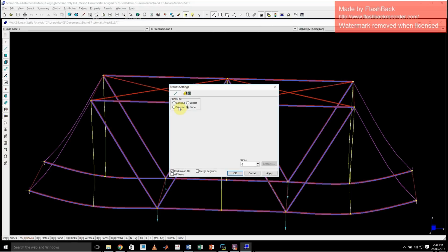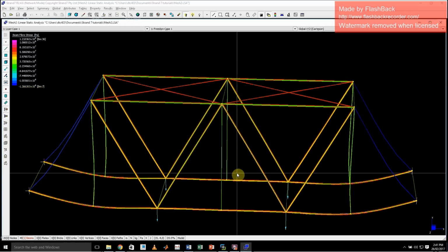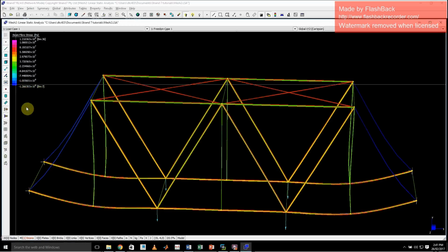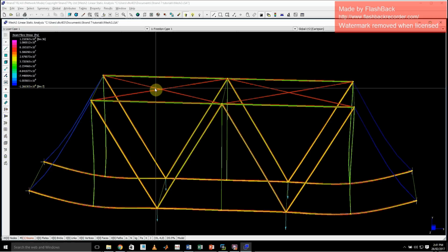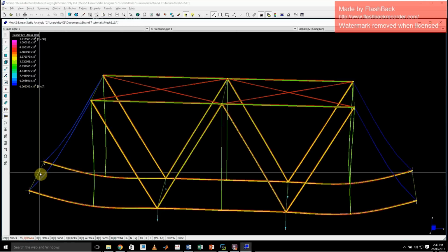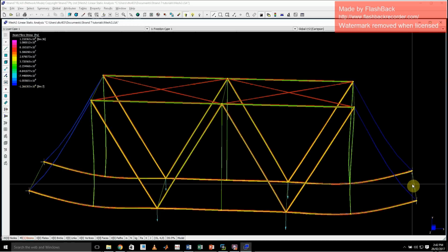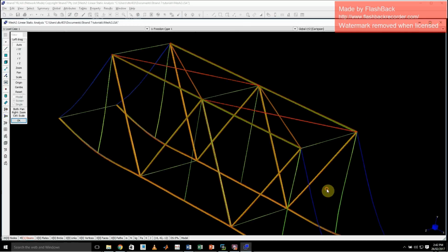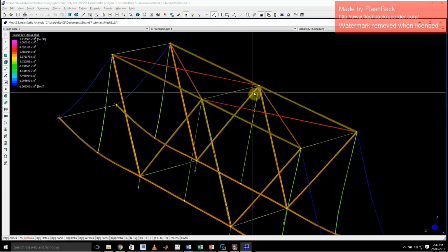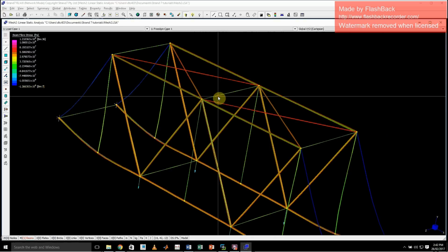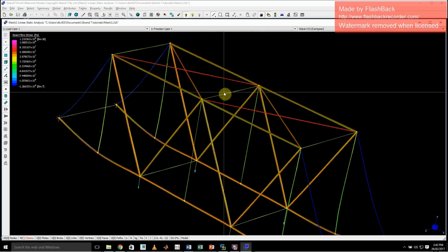We can put some contours of stress, total fiber, always total fiber. And we can have a look and say, okay, there is an awful lot of stress in those members, which we expected. There is a little bit of stress in these ones, very little stress in, say, these end members. And that makes sense because there's nothing that's really trying to compress or tension the bridge in the Z direction. Nothing's trying to pull these two things apart. So you would expect these members not to be holding a lot of load.